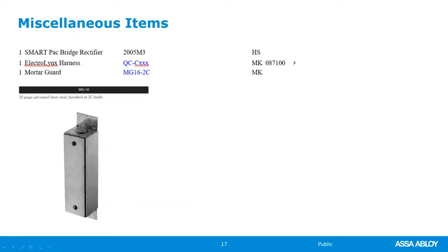And if you have masonry walls, some hollow metal frames come with mortar guards, but especially when you've got the electric through wire hinge, you want to have a mortar guard in the back so that when they fill the frame with grout, you don't have to worry, your wires can still fit in that little pocket.